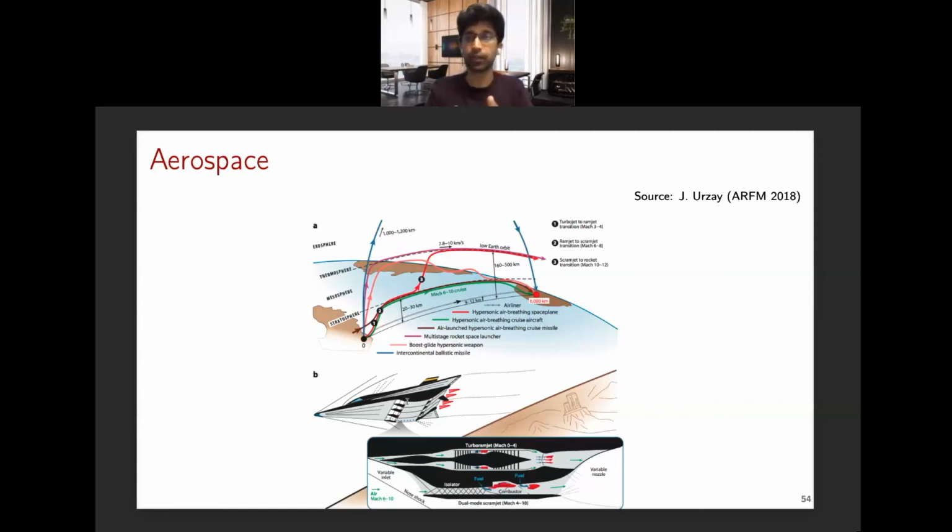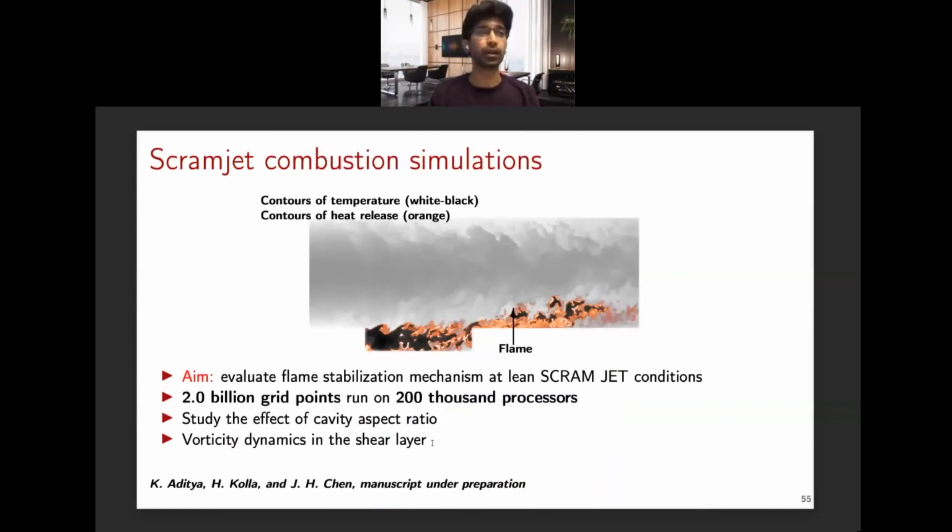It becomes very difficult. So the issue there is that the air that surrounds this candle wick, right, blows off the flame. Similar is the issue where the flow is coming at Mach 2 inside the scramjet combustor, and you want to create a low velocity region to stabilize the flame. So we are currently focusing on cavity-based stabilization method and looking at this in scramjet applications.